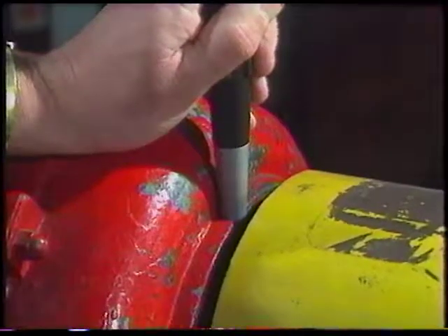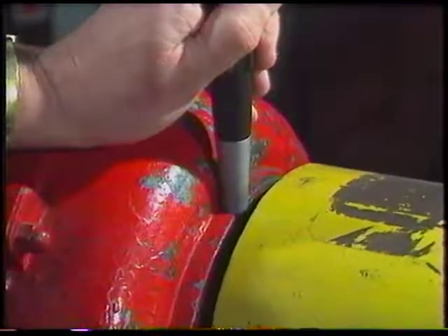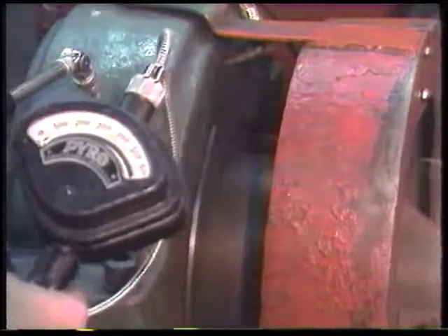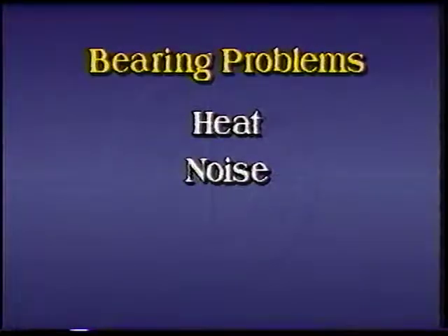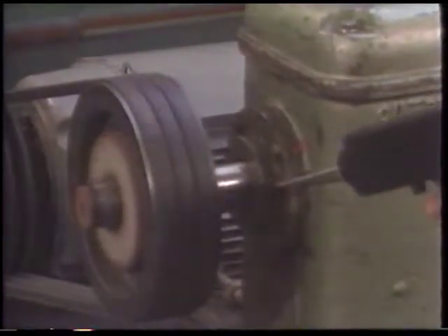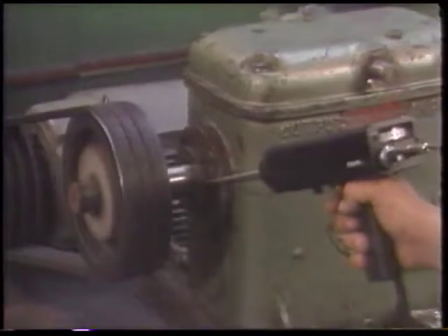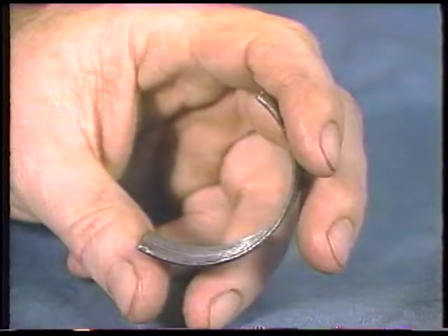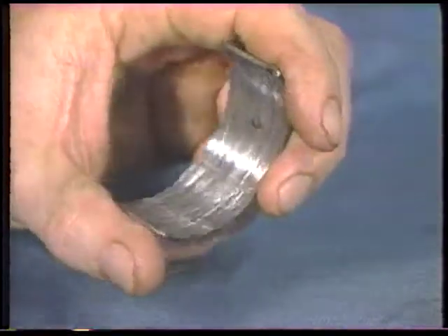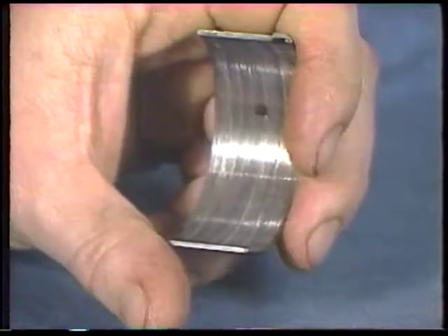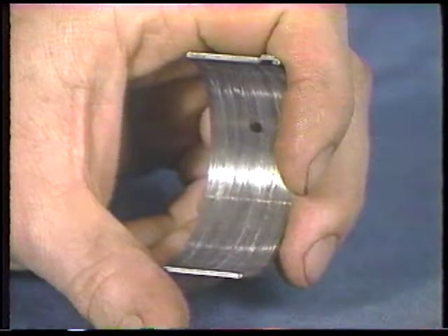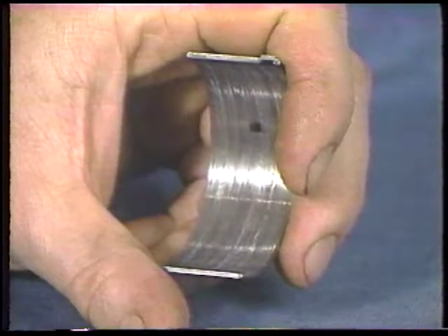Tools such as this temperature probe will make checks of bearing temperature quick, accurate, and safe. Some bearings run hot enough to burn you, so using a probe is safer than touching the bearing housing. You should also listen to the noise the bearing makes. Sounds will often indicate the bearing condition. Experience can help because you can become familiar with specific machine sounds, or you can compare sounds to those in similar applications. In a plain bearing, knocks and thumps are an indication of slackness. With a constantly changing load direction, these noises will be naturally loud and easy to detect. The sound can also indicate excessive end play or end float in the shaft.